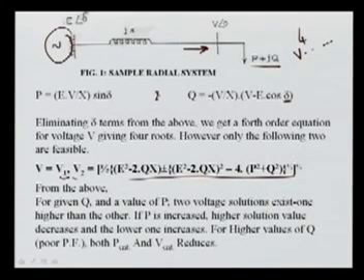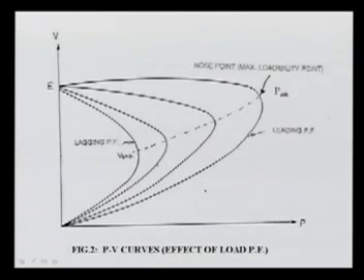You can get it very easily. So for different P and Q we can plot the curves, and the curve we plot here is called the PV curve. That means if your x axis is P and your y axis is the voltage magnitude at the load bus, we get this curve, which is called the PV curve. The tip here is called the nose point of this curve.